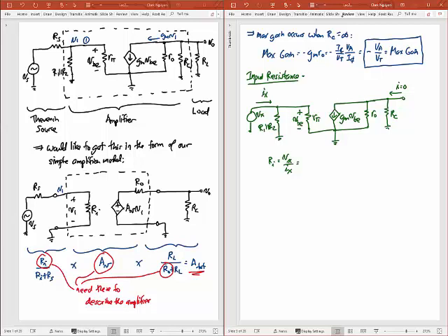And so what is that resistance looking into the ground? Well, that R pi is going to ground. That R1 and R2 are both going to ground. So basically what I have is R pi in parallel with R1 in parallel with R2, and this now becomes my input resistance. Okay? And so that's the input resistance of this circuit here, and that, if you plugged in numbers, would be equal to 1,875 ohms. Okay? Any questions about what I just did to get the input resistance of this circuit, of the amplifier?